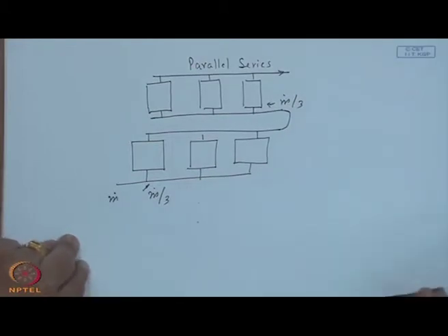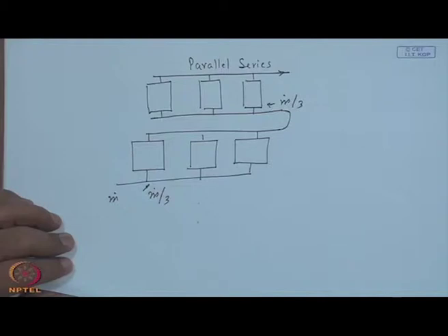So, these are the issues when you talk about not a single collector like in the classroom. We have a large system supplying thousands of liters of water, which may have 2000, 3000 square meters of area of collector with about 1000 to 2000 collectors of each 1.5 to 2 square meters of area. For n number of reasons, one has to connect them in parallel or in series or series parallel combination.